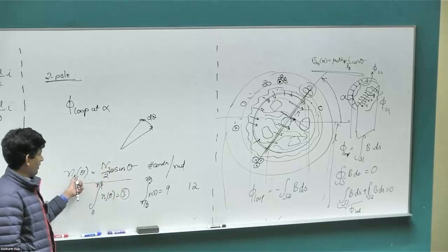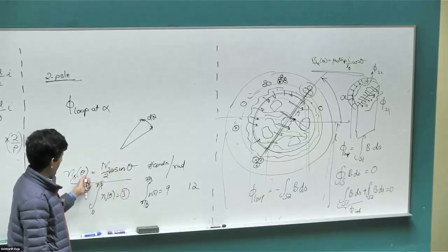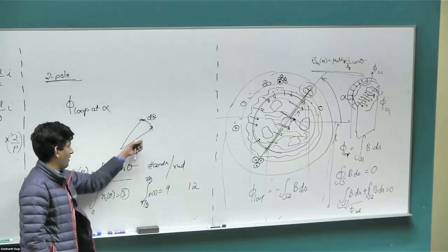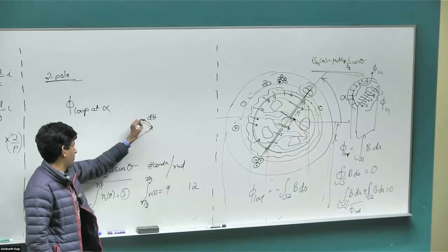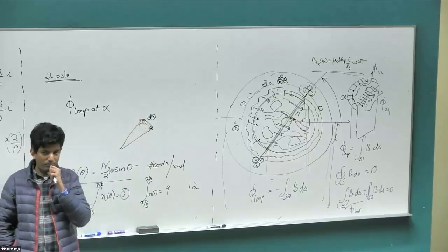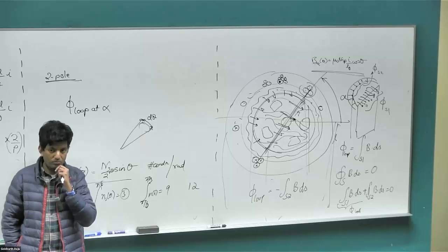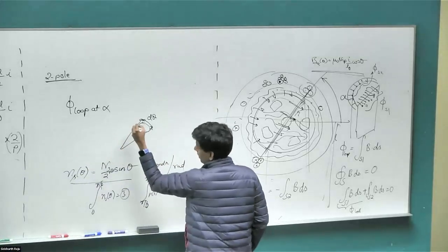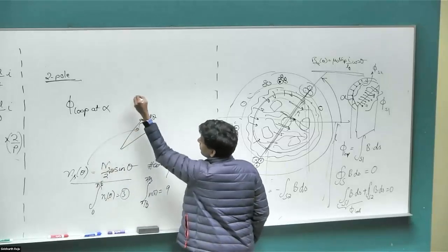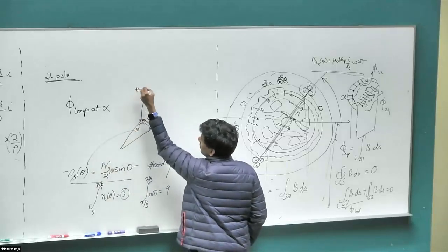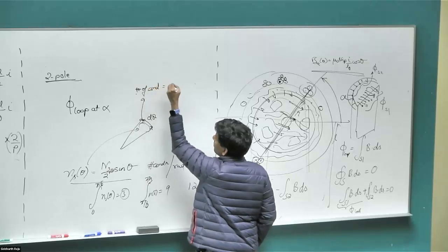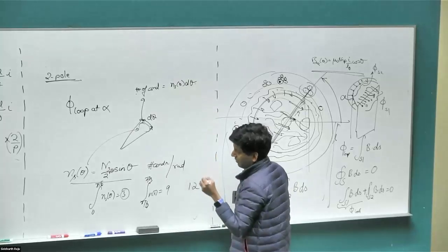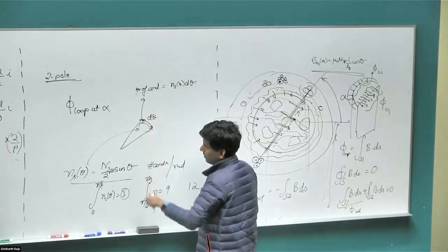Okay. So this is the conductor density. If I give you the conductor density, to figure out the number of conductors you basically integrate over the range that you want. How would I figure out the number of conductors in this range, angle d theta? So this is my density, the number of conductors. This is going to be ns of theta times d theta, right, for a tiny incremental angle.